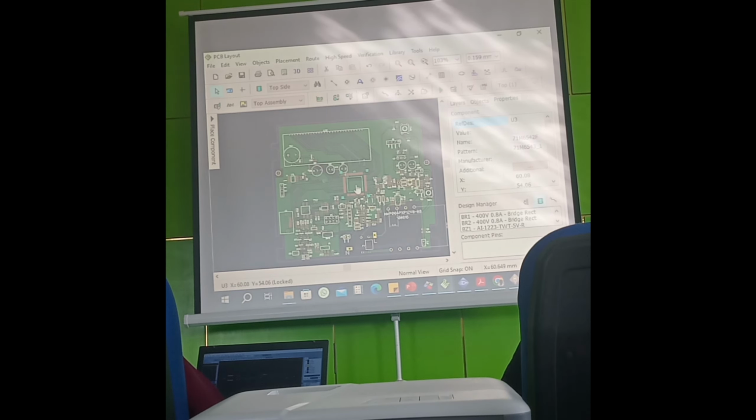Before you embark on a project like this, where you produce 40,000 of these, you will have gotten something we call a demo board. On that demo board you have everything this SoC can do, and you have the complete schematic in the data sheet from the manufacturer. So you know everything is okay.